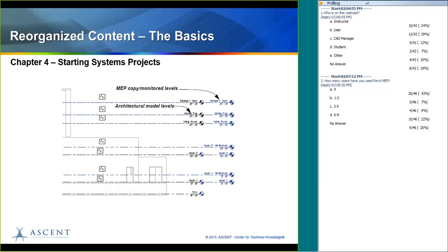And then we do teach batch copy. So if you have lots of plumbing fixtures, architectural people have already placed plumbing fixtures, you can use batch copy to get those into your MEP file, and coordination review. So not a huge change in this one, but it is a bit of the practice has been streamlined and also cut to be shorter times between topics and practices.